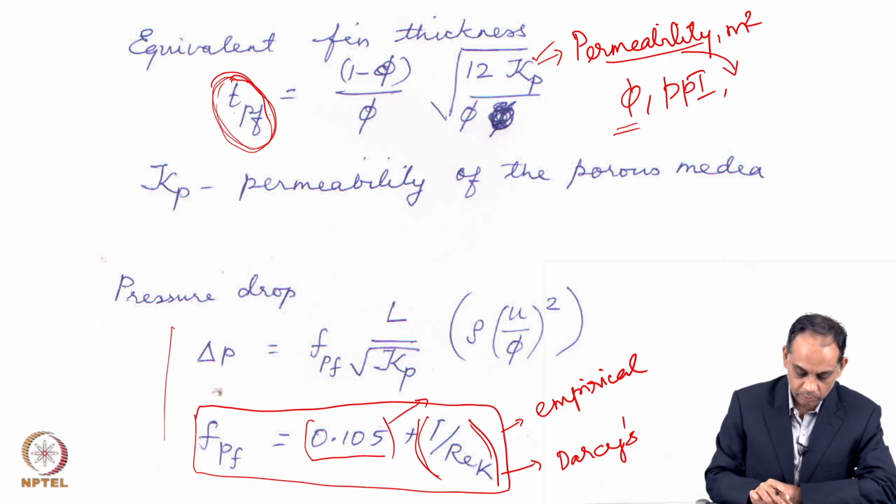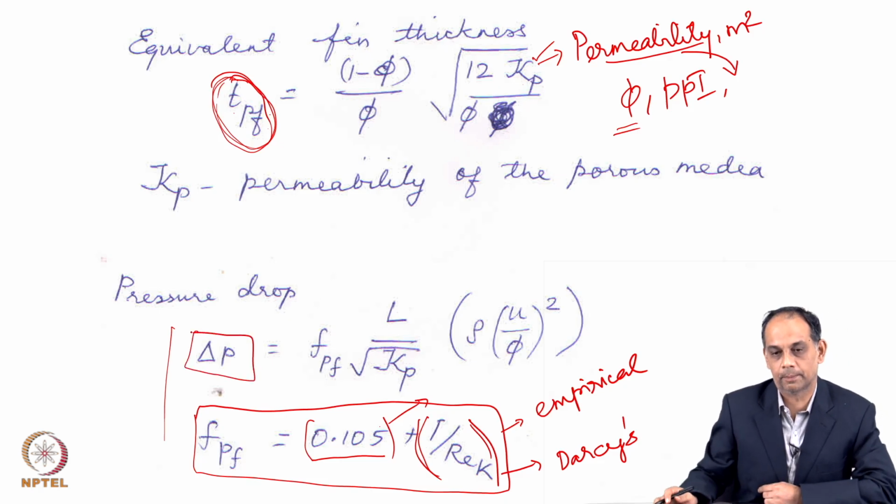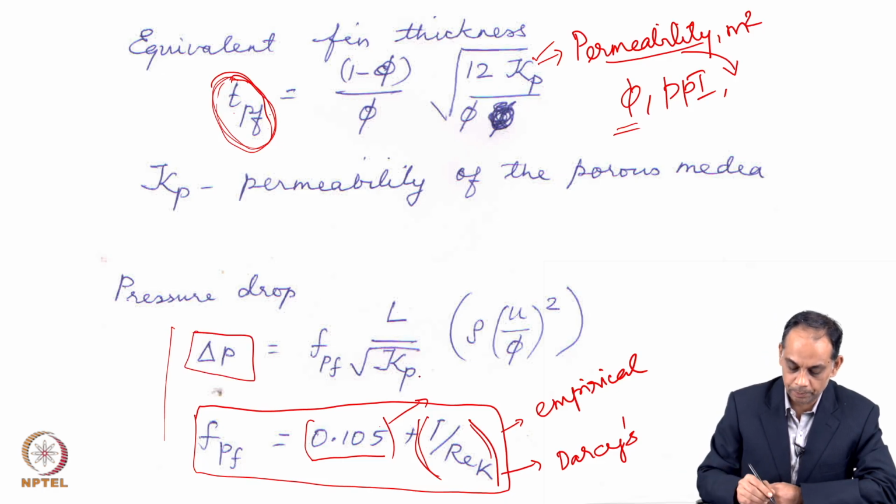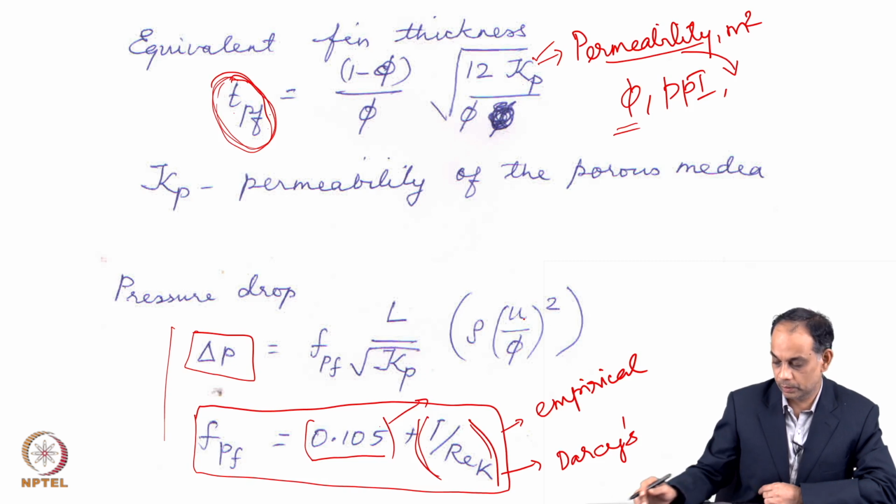Just taking these friction factor correlations, we can calculate a pressure drop for these foams, and these usually predict very well the experimentally measured pressure drop. Kappa here again is the permeability, phi is the porosity, u is the velocity, the Darcian velocity.